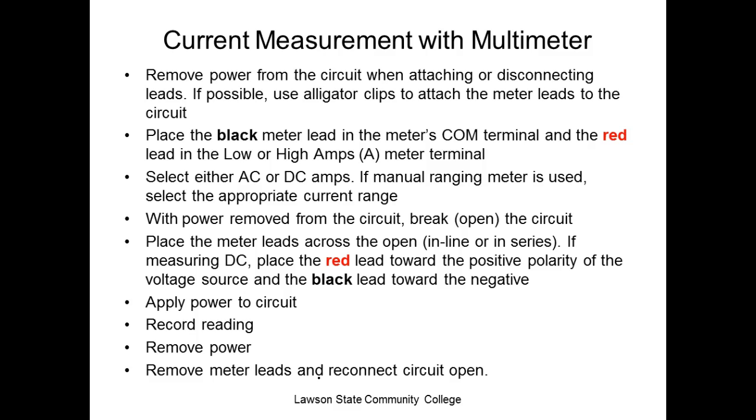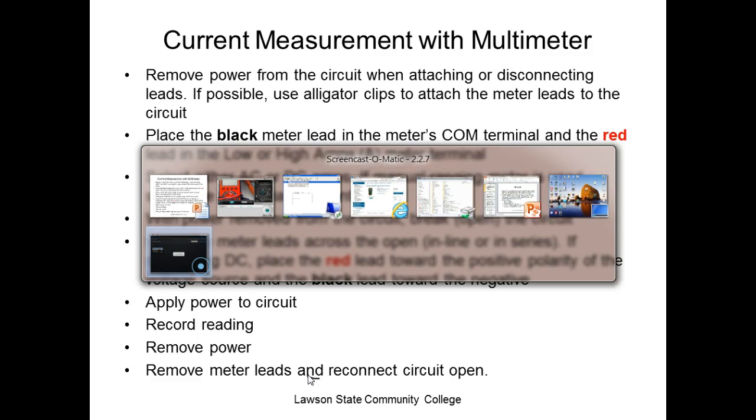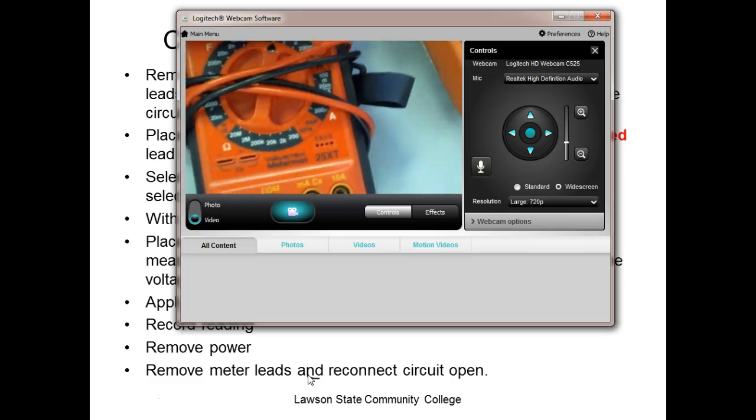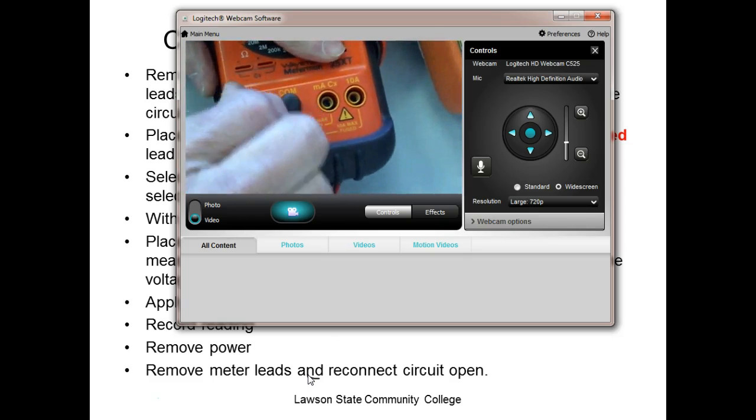Snap-on, in their meter certification, suggests that every time you finish measuring current, you pull out the red lead. So to measure current, we've got to do what?